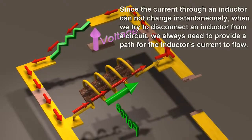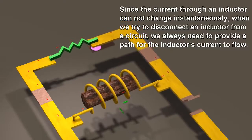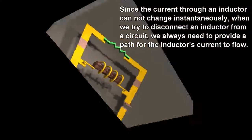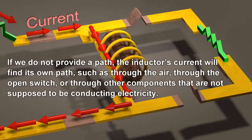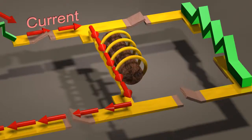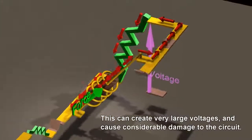Since the current through an inductor cannot change instantaneously, when we try to disconnect an inductor from a circuit, we always need to provide a path for the inductor's current to flow. If we do not provide a path, the inductor's current will find its own path, such as through the air, through the open switch, or through other components that are not supposed to be conducting electricity. This can create very large voltages and cause considerable damage to the circuit.